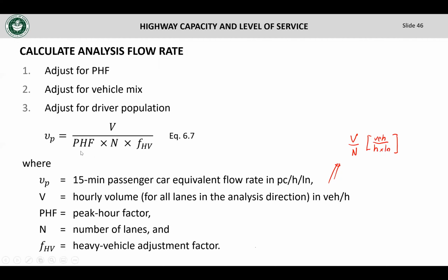And then we have two other factors. This one, the peak hour factor, is used to account for the fluctuations in traffic. So even though I'm talking about the peak hour, and by peak hour meaning the hour with most traffic throughout the day, I still have fluctuations within that hour. So I'm going to divide by a number that is less than 1 to make it higher, to account for the fact that during 15 minutes of that hour, traffic came out to be higher than the average of the hour. We have just seen queuing analysis, and you saw how demand during a period where you cannot cope creates queuing, and that queuing creates a lot of delay. We have seen that, and that's why the highway capacity model tries to account for the worst conditions. That's why they divide by this factor.